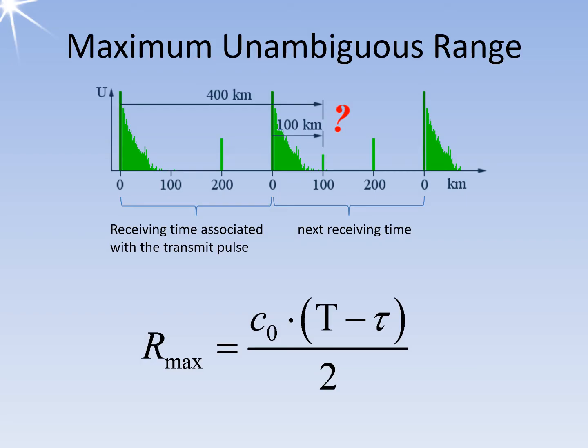The radar cannot easily decide from which pulse period the echo signal originates. The distance measurement is ambiguous. Such a measurement is also called folded range. The relationship between the pulse repetition frequency, or their reciprocal value, the pulse repetition time, the capital letter T, with the needed delay or runtime determines the unambiguous range of the radar.